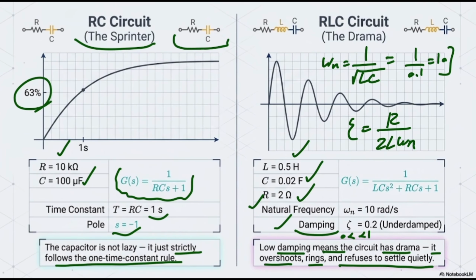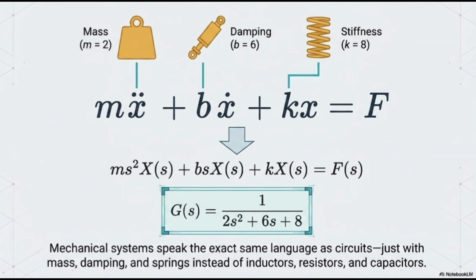By the way, when we are talking about damping, again, we are not talking about whether the system is stable or not, because the stability of the system is based on the poles. But when damping is near 0, it means your system is going to face oscillation. If your system is stable, this oscillation is going to vanish, or be mitigated, after some point. But if your damping is near zero, this oscillation would take more time.